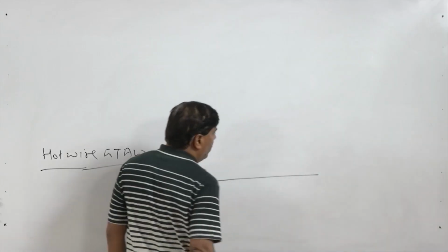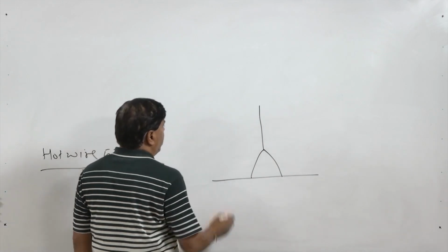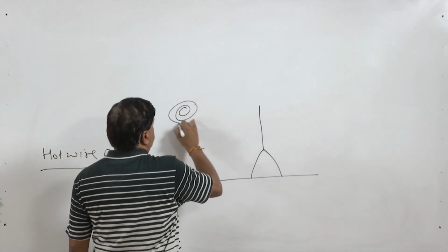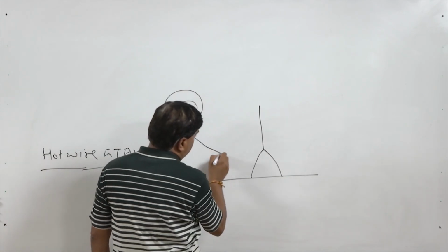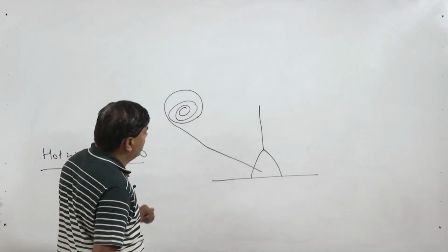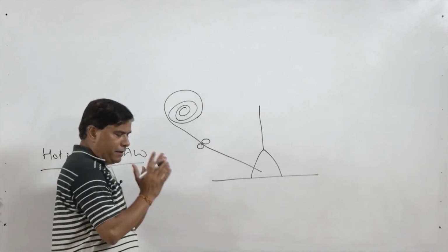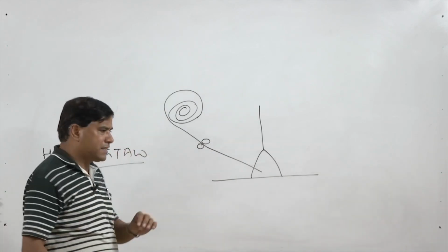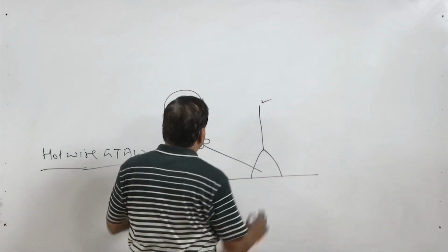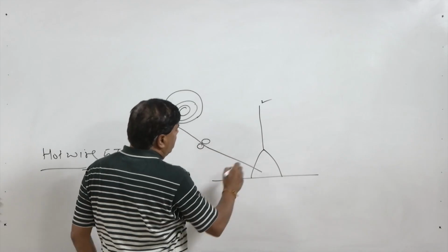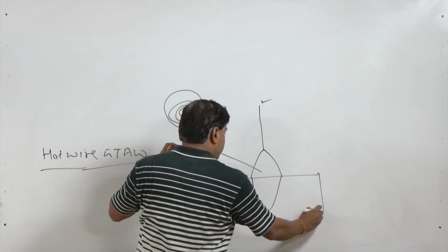say this is the workpiece, here we have the electrode and this is the arc. One automatic, like say this is the spool, and the filler is fed through a filler feeding device, not the electrode, the electrode is here, but the filler is fed into the arc zone, so that it melts and forms part of the weld.